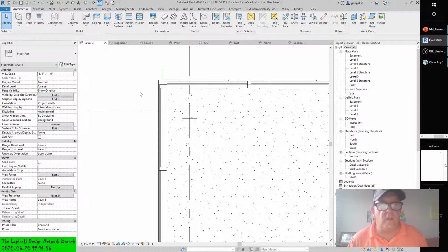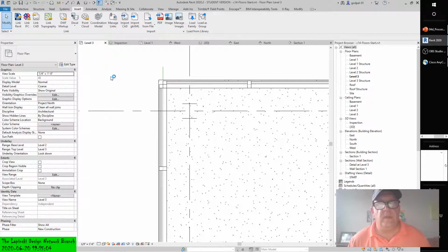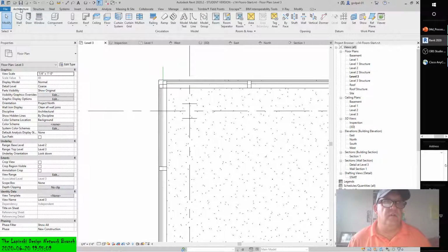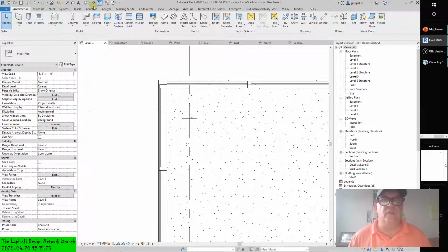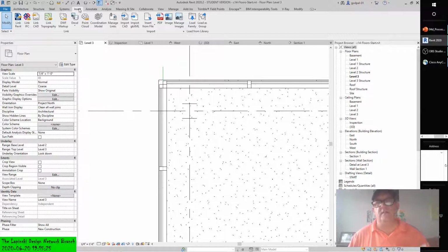So if you don't have a structural deck profile loaded, finish the floor by selecting Finish Edit Mode, then select the Insert tab on the ribbon. Well, you can do it from here, and if you have the luxury of inserting anything here. If you're in a tab and you try inserting things, sometimes you can get a message that it's not appropriate to load anything from that tab because it's not in the right category. So you have to be kind of cognizant of that. Insert usually takes care of all that. It doesn't. It's really not tab tool discipline specific. So that's going to help us with this particular exercise.